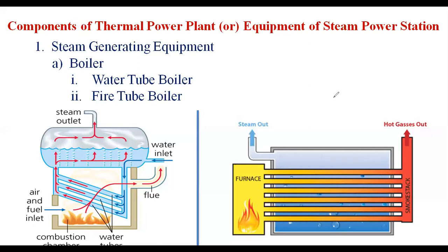But the coal storage plant, coal handling plant, ash storage plant, and ash handling plant are a separate section. That is, we import the coal from the coal mine by railways, roadways, or seaways, and unload the coal. After that, we prepare the coal with the help of coal pulverization, that is, crushed into small pieces or powder by using a ball mill, hammer mill, or bowl mill.